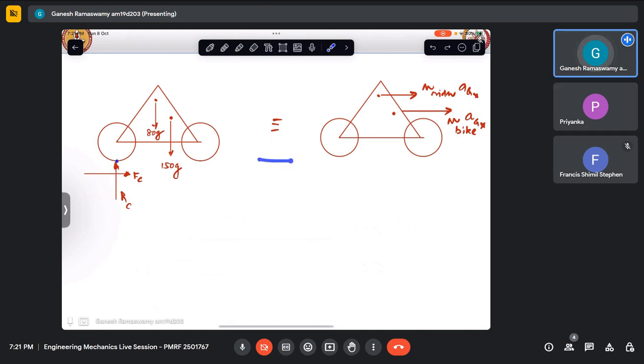You are talking about a box where, if its impending motion is this way, I will apply friction in the opposite direction. Fine. We are talking that motion is being achieved by the rotation of this wheel. At this instant, if there was no friction, the tendency of this point is to go that way, which is opposed by the friction from the road, which is what propels the vehicle forward.